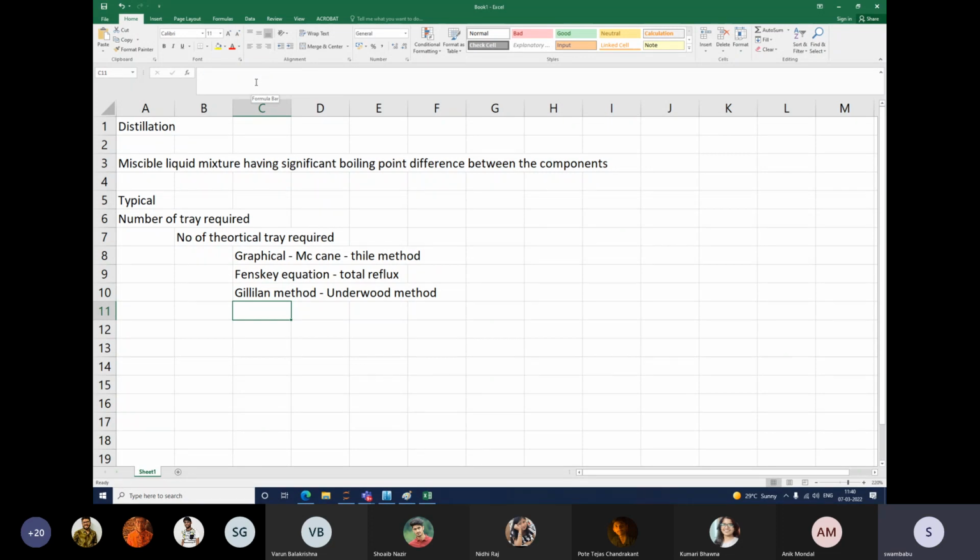What we do is we write the mass balance for each tray, and we solve all these mass balance equations to find out the expression. It is the same thing we do in the McCabe-Thiele method. McCabe-Thiele is shown in the form of graphical representation, whereas these are shown in terms of the mass balance expression. Both are the same.